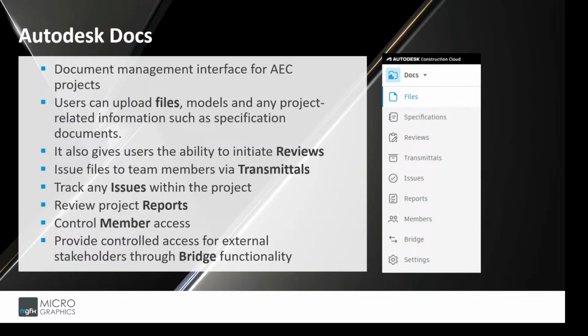Autodesk Docs allows administrators to configure automated approval workflows. These can range from 1 to 6 steps and support both serial, one person after another, or group, which is parallel reviews. This system ensures that documents transition through proper stages, such as passing from work in progress to shared or published, only after being checked and authorized.